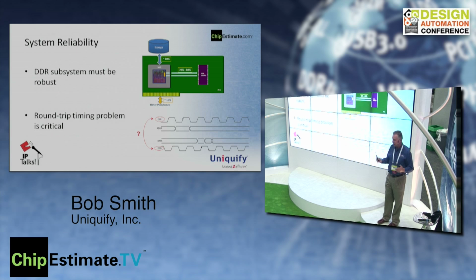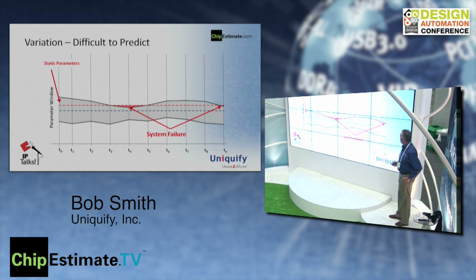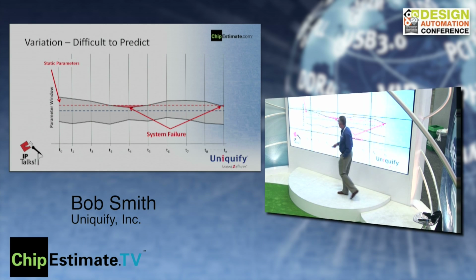And solving that problem is typically done on the bench. In the past, when the SOC comes back, the engineers will go through lots and lots of samples, and they'll measure under different conditions what the delay looks like and the phase relationship, and how much do I need to compensate for it, typically using delay registers in the PHY. Very manual process. And it's difficult to predict, especially when you consider what's going to happen out in the real world.